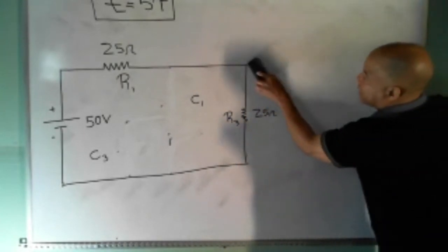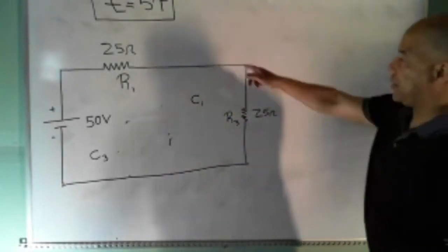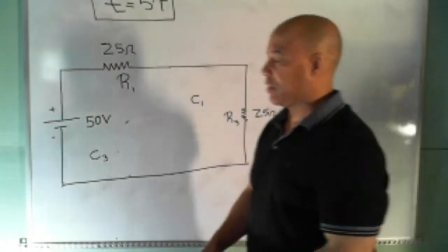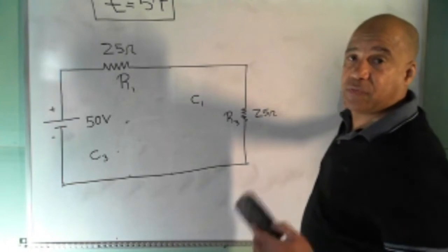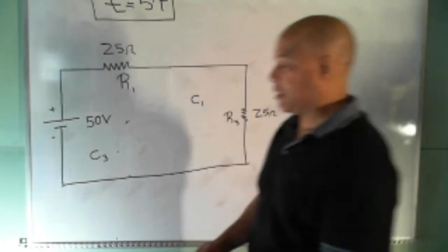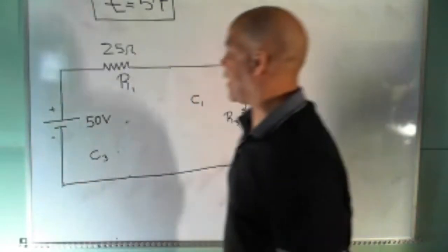The equivalent circuit is this one. And so you can easily see that each resistor, all the ones I erased, the voltage drop was 0, the current was 0. But for the two that remain, each resistor is going to get how many volts?